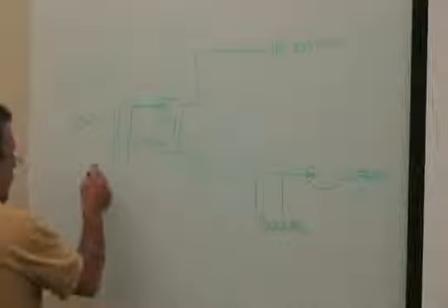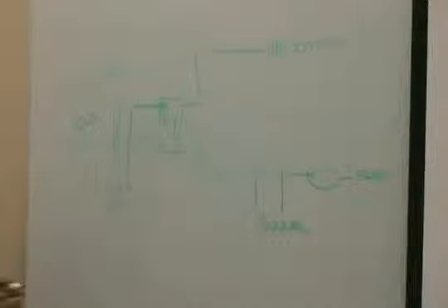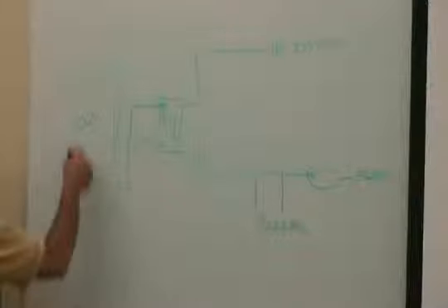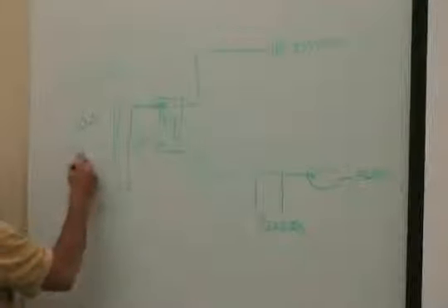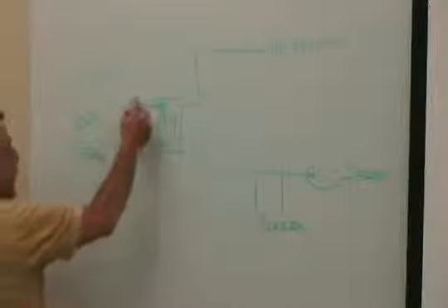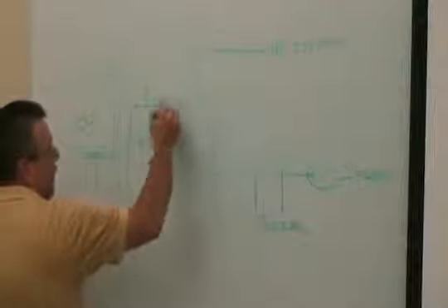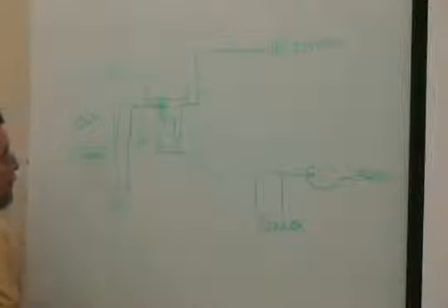This way, I've got my standard basin here, but in the wintertime, if I know I don't have any simultaneous heating and cooling, I can shut this down, or I can put a basin heater in here. You don't have to worry about freezing. This is inside the building. Again, you might put thermometers on both sides of this just to visually check it, and pressure temperature taps so that you can check it with gauges and temperature.